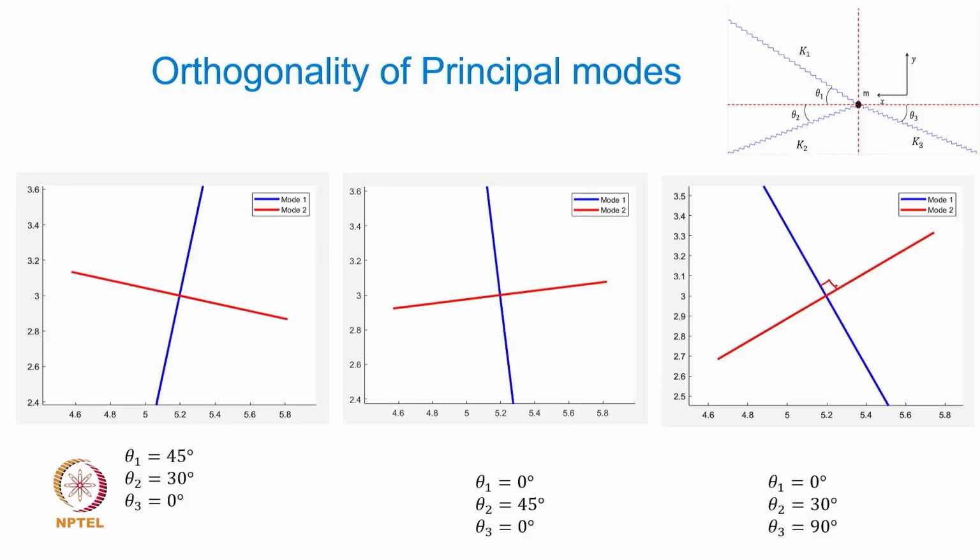That's precisely the meaning of that, and it's quite similar to the case of the principal stresses and principal planes that you might have studied in solid mechanics, where a stress element subjected to different applied stresses has planes along which only the normal stresses act, and those 2 planes are again orthogonal to each other.